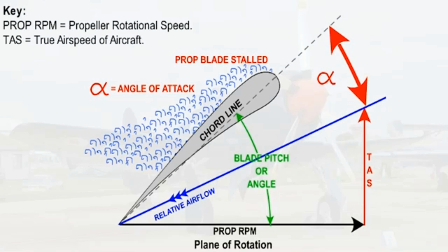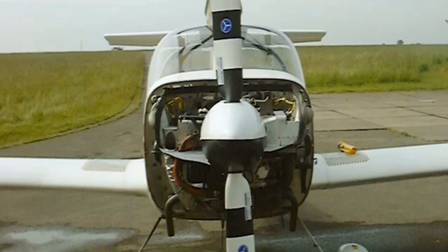The conclusion that must be drawn is that for a given fixed pitch, a propeller will only work efficiently at one combination of true airspeed and RPM. All these considerations illustrate why more advanced aircraft have engines which are fitted with variable pitch propellers. There are several different types of variable pitch propellers. Here are some which the private pilot may come across.